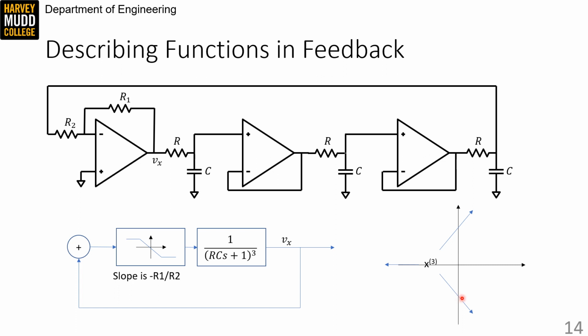And when the poles are on the j omega axis, if there's a perturbation that reduces our amplitude, the describing function gets a little smaller, pushing them back onto the axis. Or if there's a perturbation that increases our amplitude, the describing function also pushes the poles back towards the axis. Excuse me, when the amplitude decreases, the describing function gets larger, pushing them back to the axis. When the amplitude increases, the describing function gets smaller, pushing the poles back towards the axis.